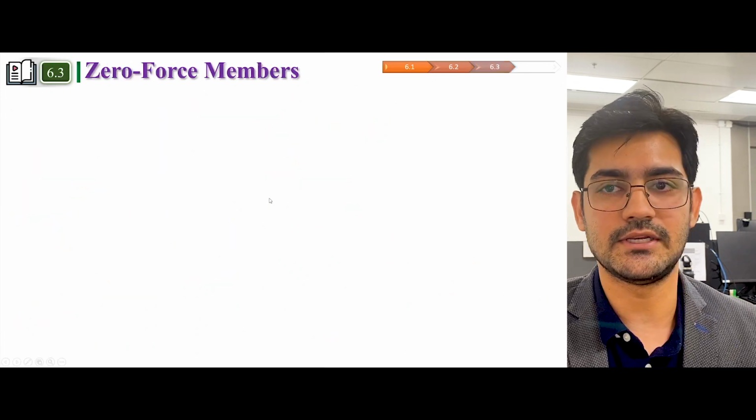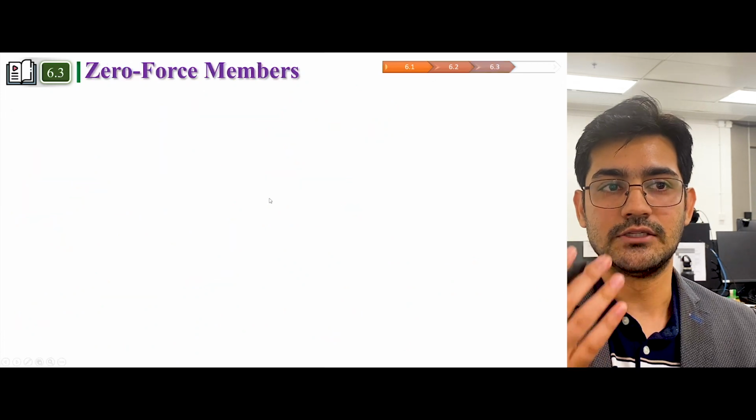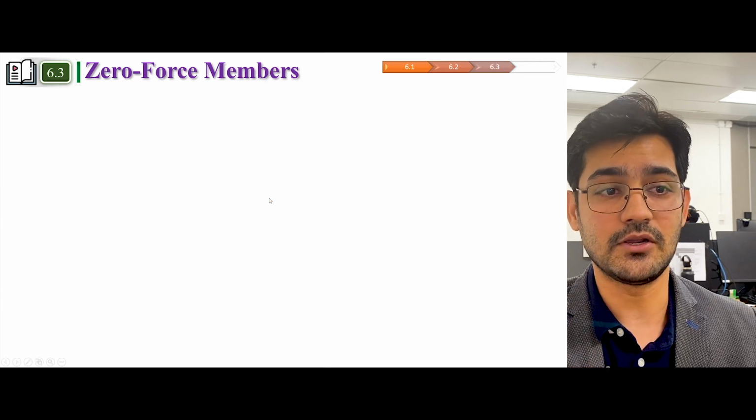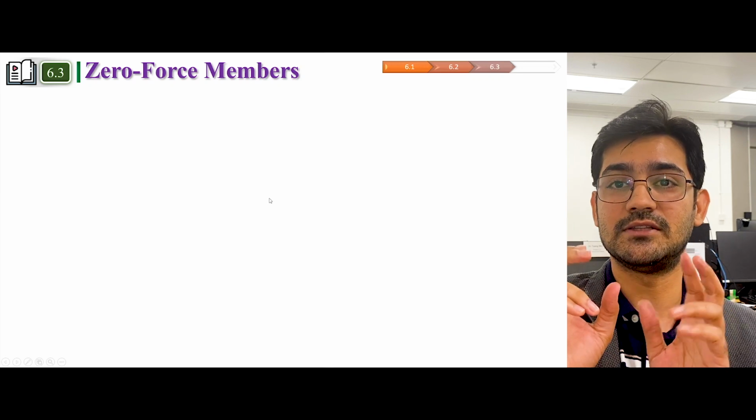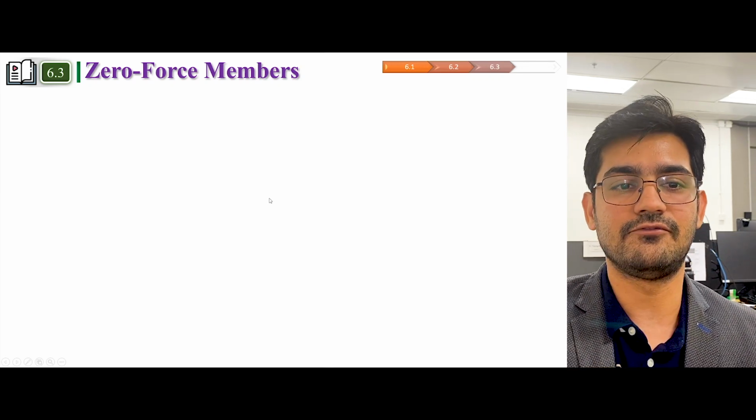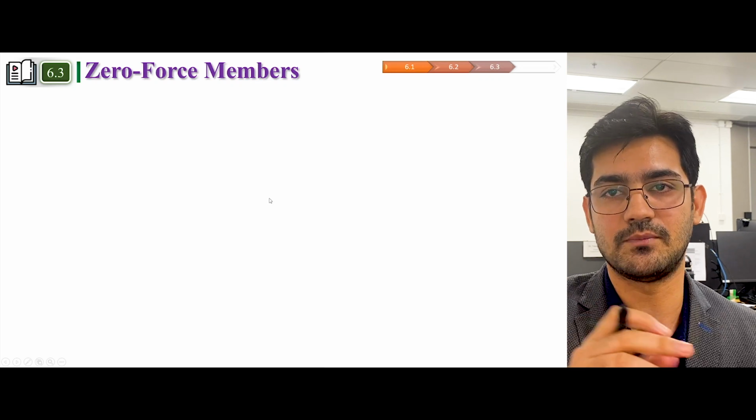Now the next section is about zero force members. It is also important to understand what zero force members are, because truss analysis using the method of joints can be greatly simplified if we can first identify these members which support no loading.